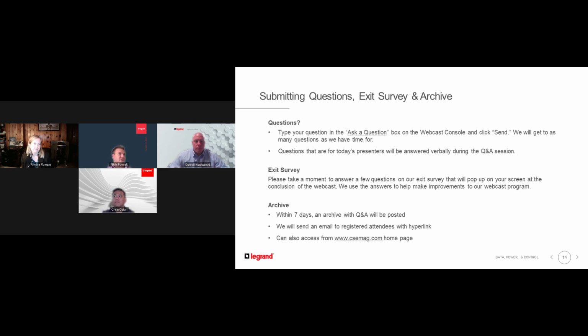Sure. Yeah, that's a great question, right? So obviously the overhead power distribution systems like busway are a very static type system. I always like to explain it as it goes together like Legos, kind of snaps in place. You have some joint kits. But the biggest part of the failure is typically due to the install. That's why it's very important to specify things like the manufacturer to come out and perform the startups.